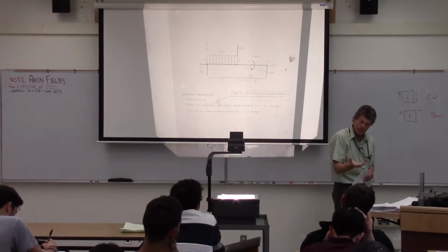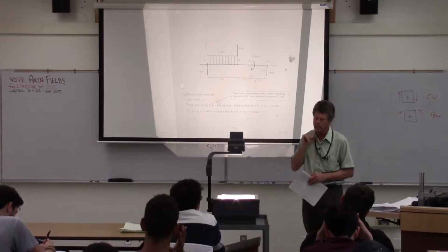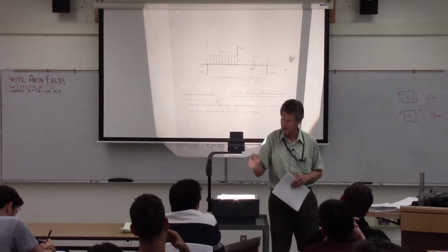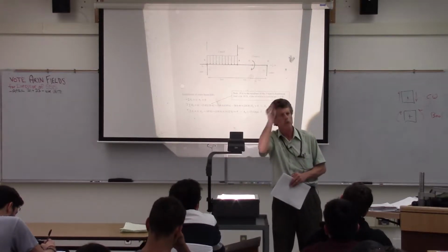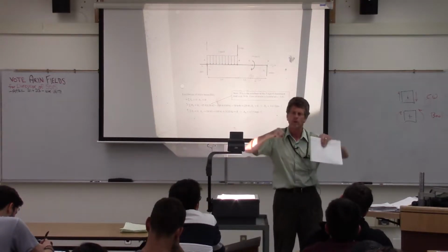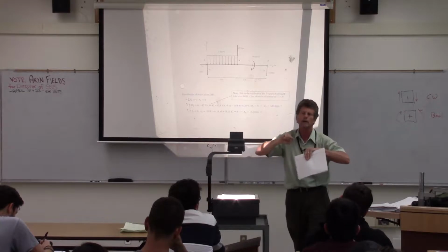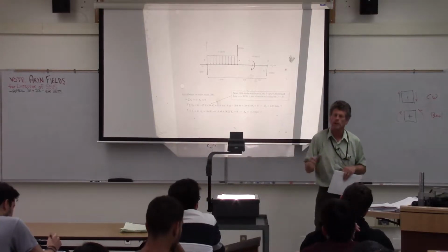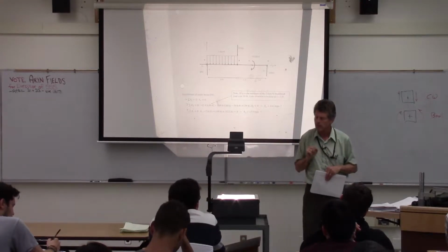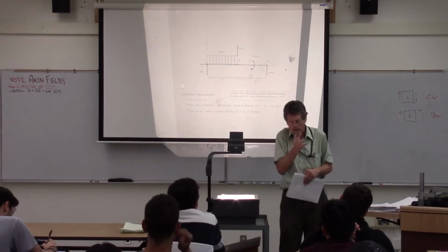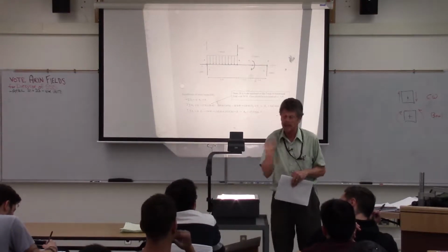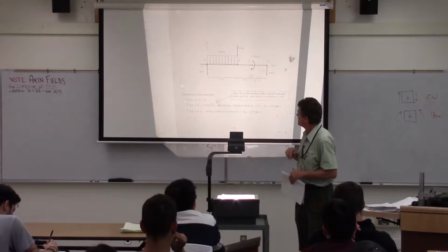It's just the opposite in steel. If you have positive moment in the middle of the beam, they're going to show it on the top side because you have compression buckling of the top flange that you have to worry about. So you basically have to beef that up somehow. So where you put it doesn't matter, but the positive and negative connotations are going to be the same.